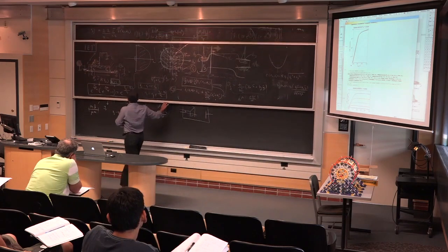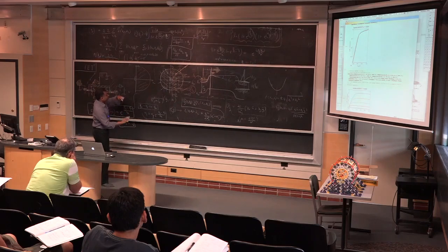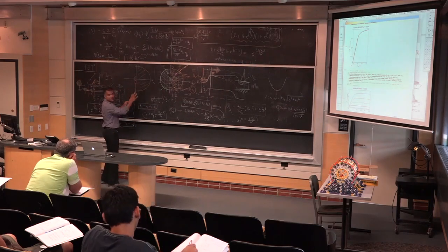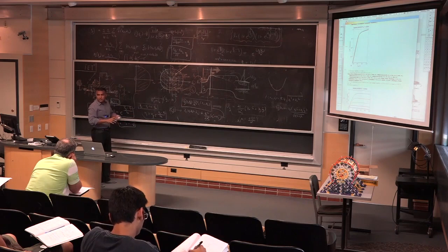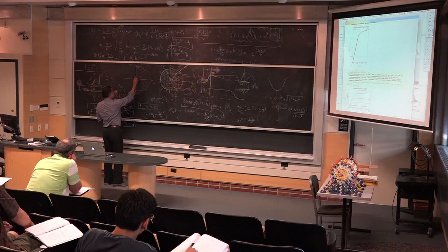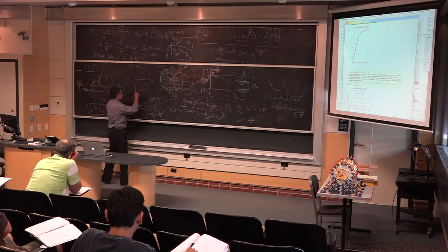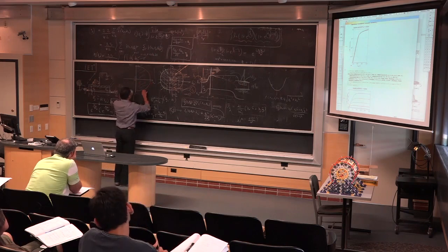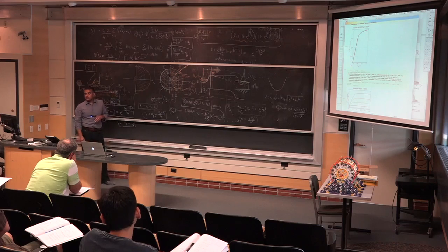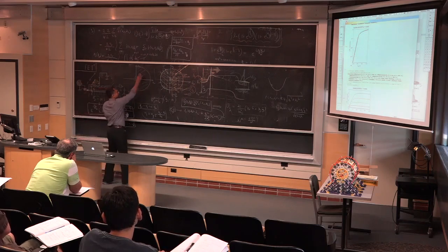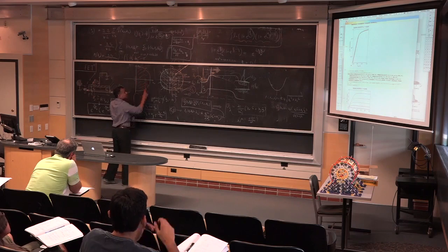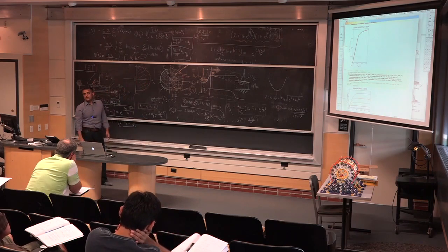That's a nice point to realize, once your drain voltage is large enough, what is happening in K space, right? The electrons are injected from the source and the drain. But once the drain voltage is large enough, this thing shrinks and shrinks, and then it completely goes away, right? Then all the electrons that are in the source injection point have come from the source, and their density is not changing anymore, right? So they're all moving to the right, and they're already carrying. You have already summed up the velocities, and the current is not changing anymore. Does that make sense? So that's the reason in this picture.